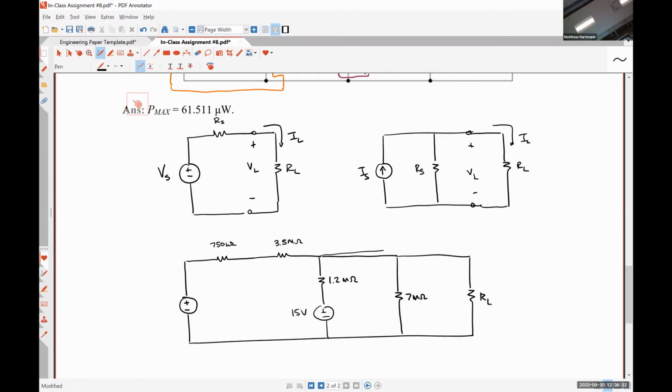Sorry, what was that? Exactly right. So we multiply the current times the resistance, just Ohm's law effectively. So we're going to have, if I can get out of this mode on my calculator. I don't know what I did with my TI calculator, so I'm left with this Casio that I barely know how to use. So somebody else do the math. I literally can't figure out how to get out of the equation solver on this dumb thing. Yeah, I finally got out of it. Thank you. So 27 times 10 to the minus 6 multiplied by 750 times 10 to the positive 3 gives us 81 over 4, which is 20.25 volts.